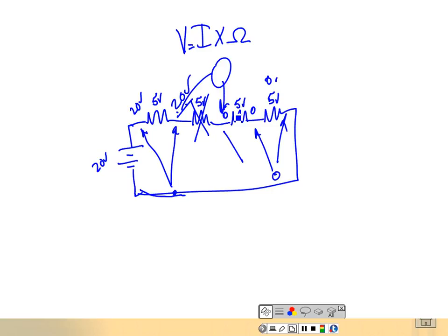But understand why the entire voltage appears across the open, because everything else is acting like a wire. Why is it acting like a wire? Because there's no current flow to cause them to drop a voltage. So they don't drop voltage, because the only way I can get a voltage drop, V is equal to what? I times the opposition. If I have no I, I have no voltage drop. Pieces of wire don't drop voltage, right? So they act like pieces of wire. So that 0, that common, comes all the way through all those loads and sits on this side of the open. The voltage comes all the way through all those loads because they're not dropping, and it sits across the open. So opens are real easy to find.